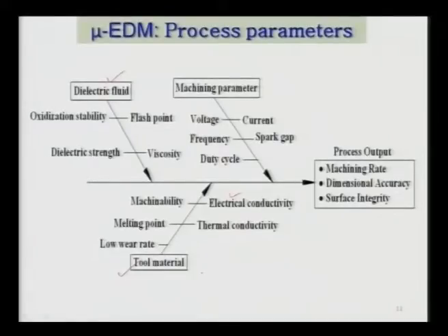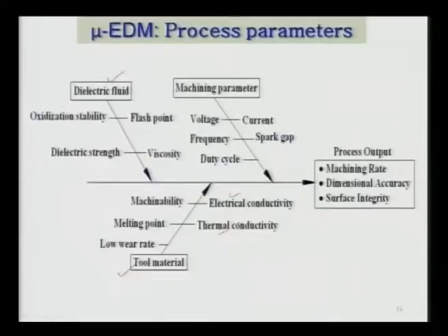I do not say exactly the replica, and tool material should definitely be electrically conductive. The melting point of the tool material should be as high as possible, so that the wear of the tool is minimum. It is also a function of thermal conductivity that will decide the temperature of the tool, and definitely the tool material should have a low wear rate.